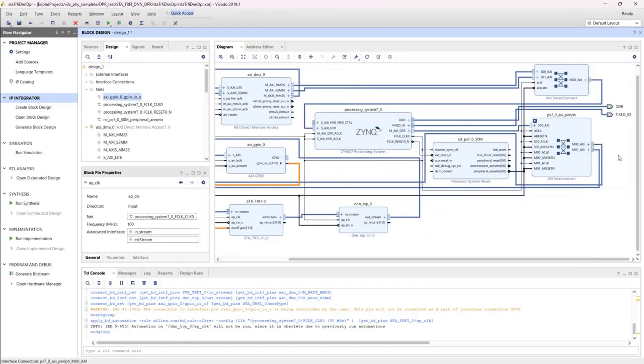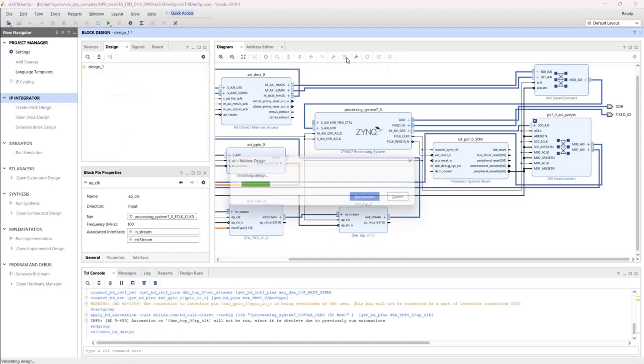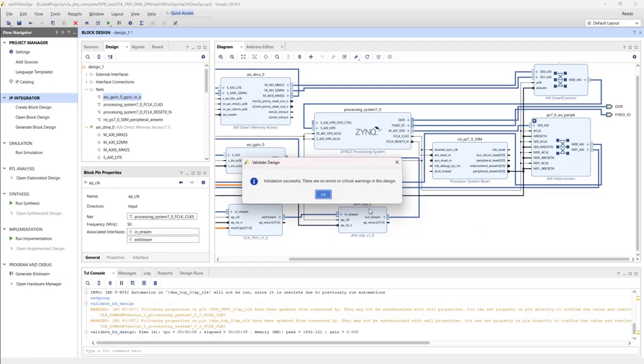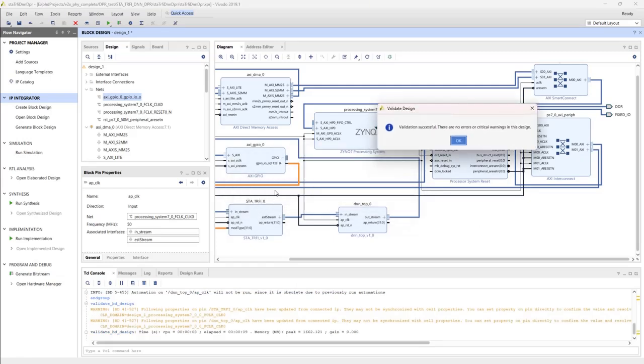All right, so our block is ready. Let's validate it. See if there is any error or anything. Okay, yes. So if you had not created the blanking IPs using the IP packager the way I showed, you can see that if we had only used those .v files, the blank v files in here, the validation would not have been successful, right?